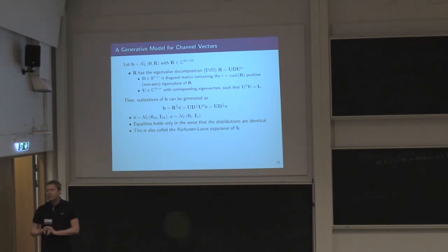Yes? What I have read about these models is that the independent model is more generally used in trying to simulate things and in theoretical investigations. And these types of models are mostly used when we keep the practical constraint that antennas are very closely located to each other. So you haven't told us how we select a model, because in theory we always assume that they are all independent, and from the practical point of view, we should take the antenna correlations into account because of the close coupling.